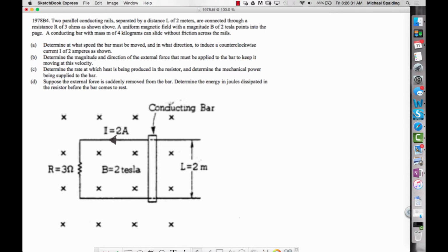There is an induced voltage. An induced voltage is happening because of the flux in this loop. The loop is this area that I'm circling right here. We're focusing inside that area. Inside that area, there must be a change in magnetic flux. Whenever magnetic flux changes, you get an induced current. Now, there happens to be an equation that applies specifically to this. Induced voltage in a loop, when it's a bar moving through a magnetic field, the equation is BLV. Boom.